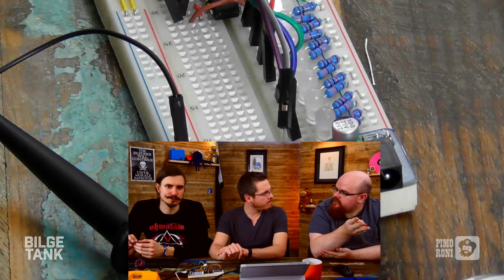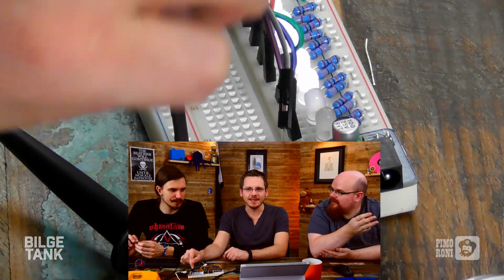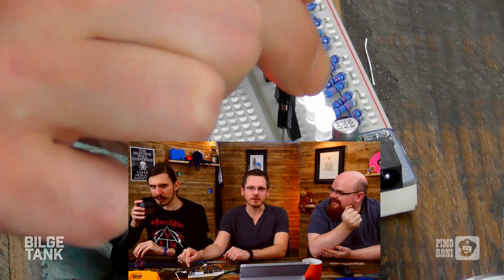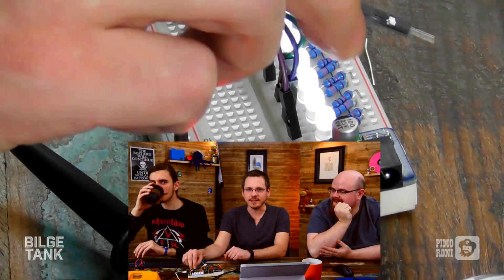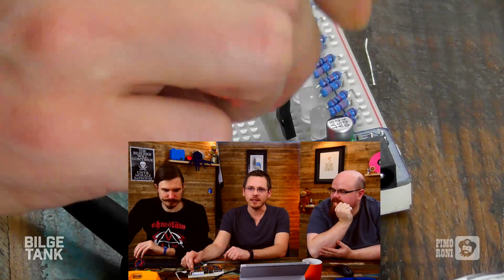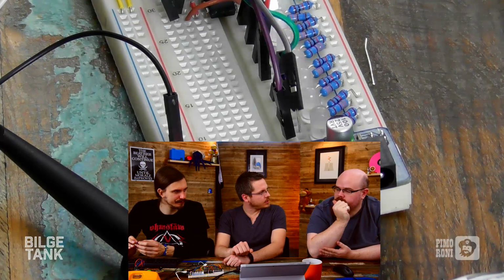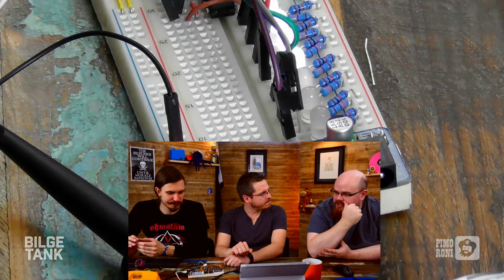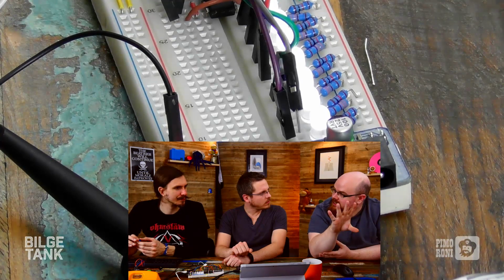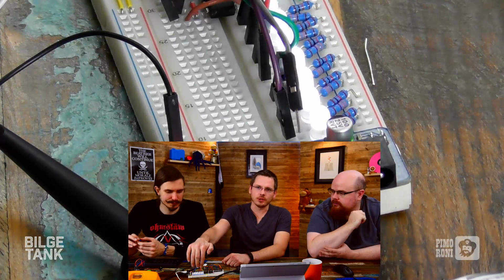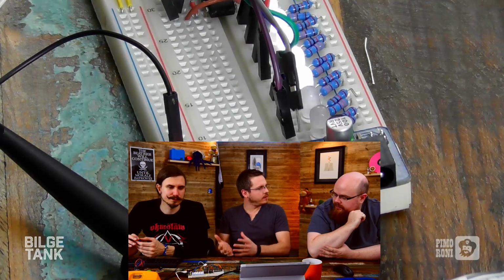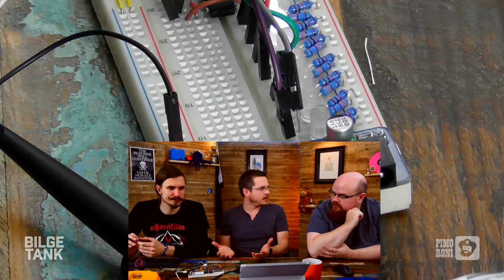So that's not actually the 3 bits, though, is it? Well, it should be 8 LEDs, but I ran out of space on the breadboard. So there's 7. There's actually a dangling lead here for the 8th LED. But basically, you would need to then encode that into your binary. Okay, so we're not binary yet. What we've got is analog to digital, so we've got discrete readings now. We now have logic level discrete readings that we could then convert into a binary representation, essentially.